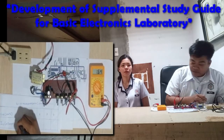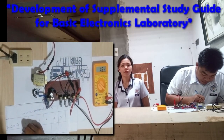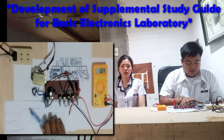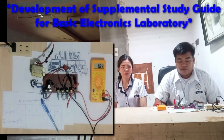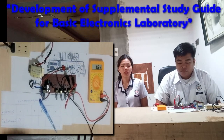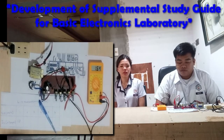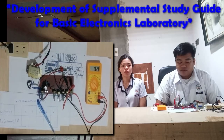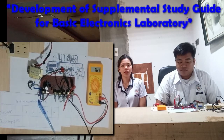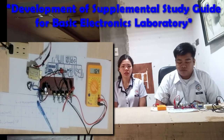Record this value of collector current in milliamperes immediately below the collector emitter voltage value of 1 volt in the table provided in figure 3-3. Now complete the table in figure 3-4 by adjusting collector emitter voltage to the remaining values indicated and recording the corresponding values of collector current. To do this, simply repeat steps 5 and 6 above for each of the remaining values in the table.